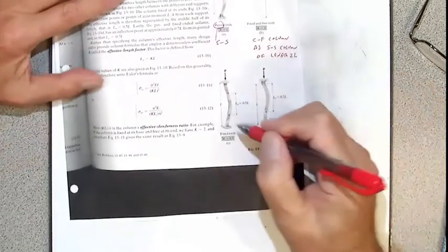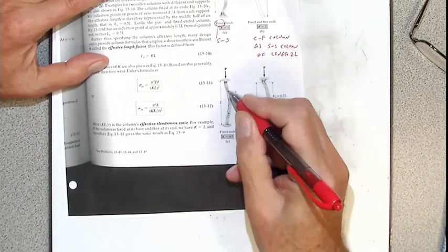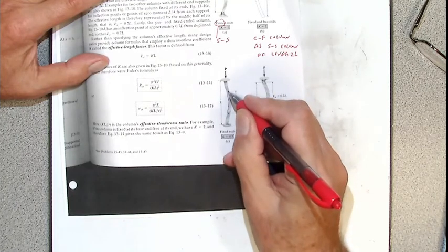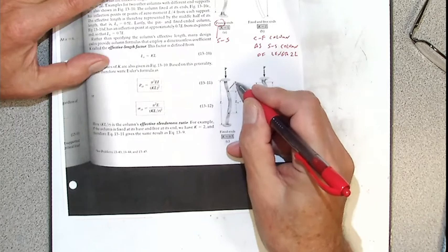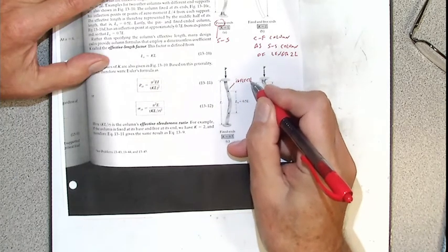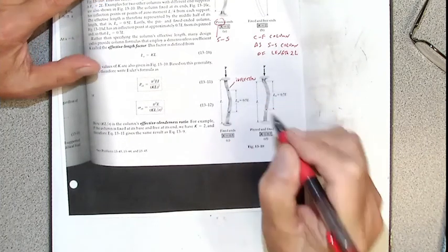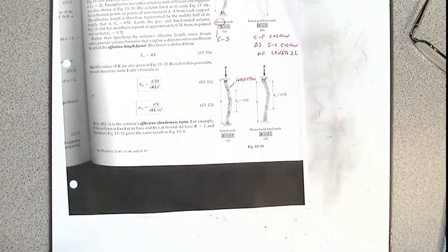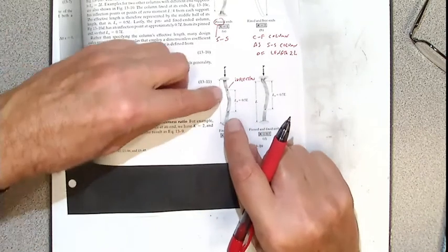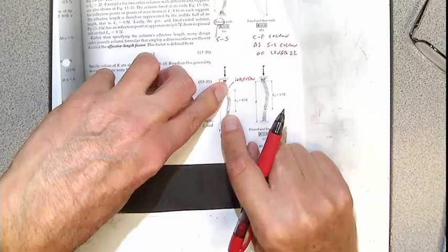Okay, here for clamped ends. So that is a buckling mode. So we can find the distance actually between points of inflection. And the distance between these points is half L. So that means that the length, as it were, of clamped beam is half length, and then beam is simply supported here. Therefore, buckling load will be 4 times bigger.